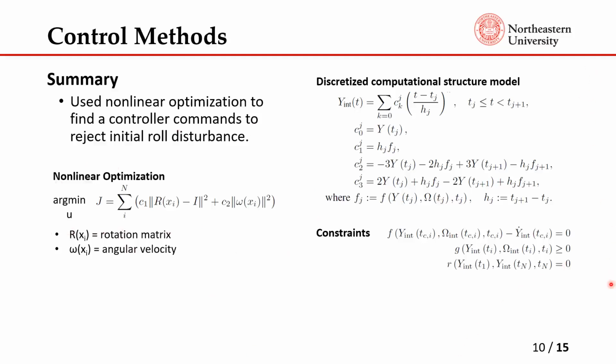The constraints are developed using something like finite element methods: each wing is segmented into discrete plates, and each plate has a control point for the aerodynamic forces. We want to find inputs that follow these constraints and minimize the perturbations throughout the period. More detail can be seen in the paper, but that's the general idea.